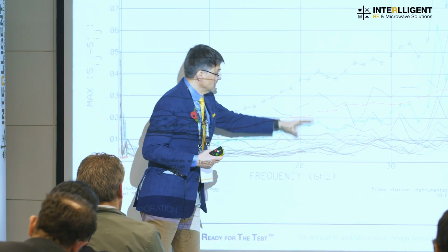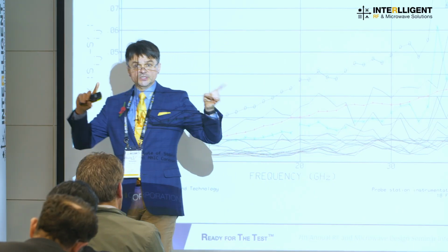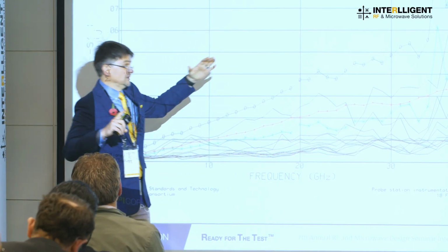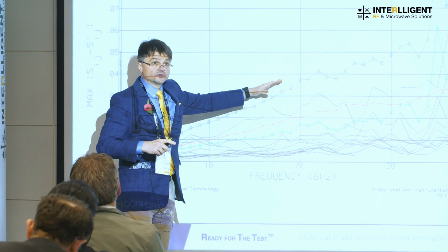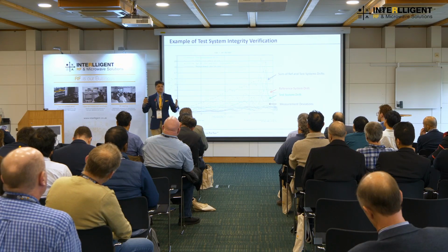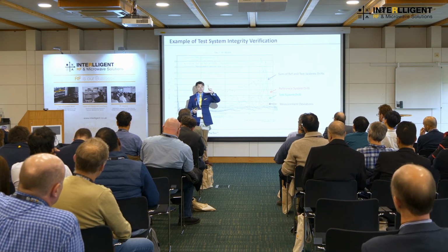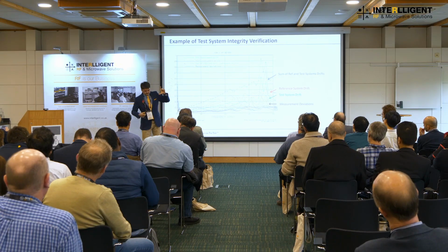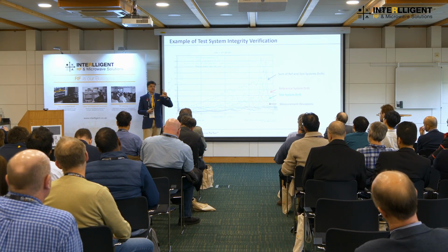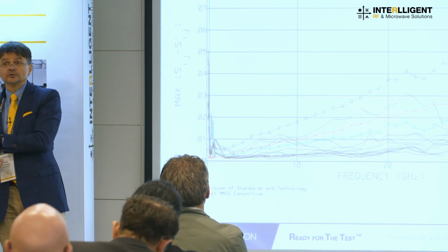Even if there are some noticeable variations in the S-parameters between these two sets, if they are smaller than the drift of your two setups, there is no difference. We can't assume that the data are not identical. And that helped at that time to compute this confidence interval in your measurement data and report it even without establishing the traceability chain on your measurements.